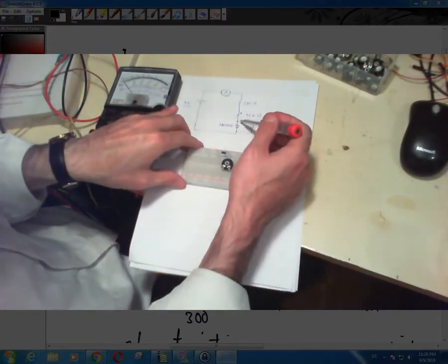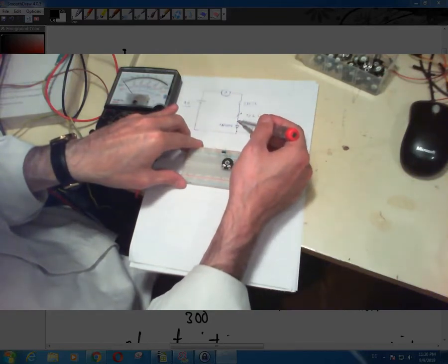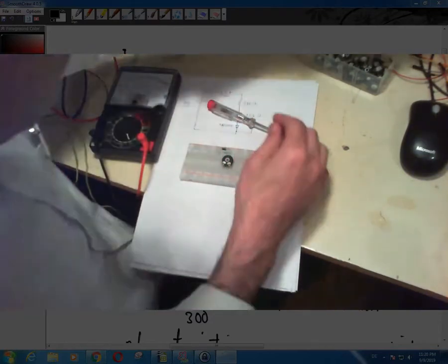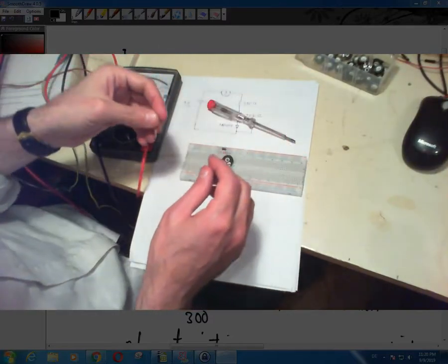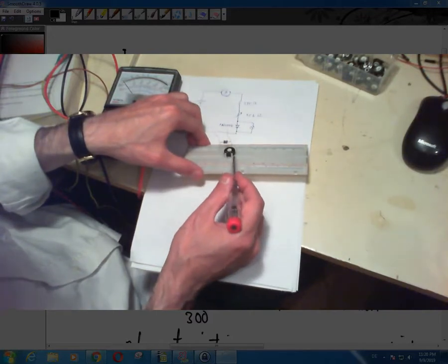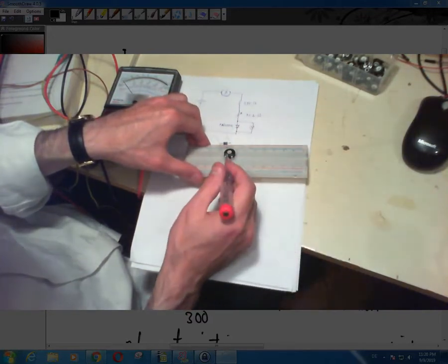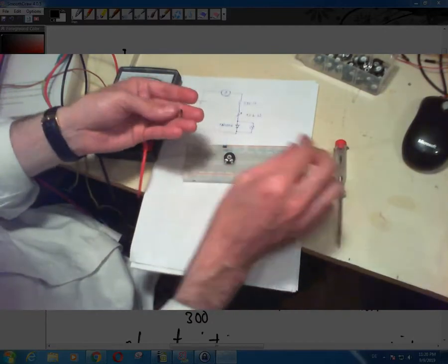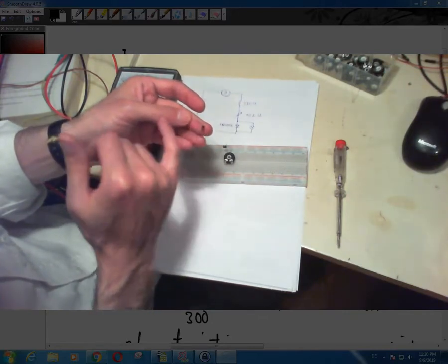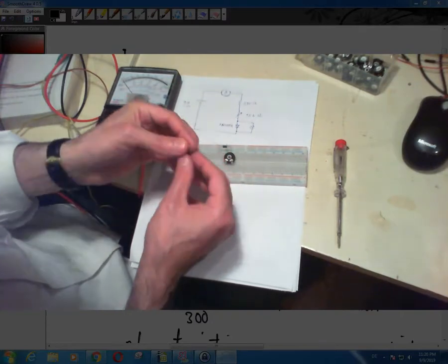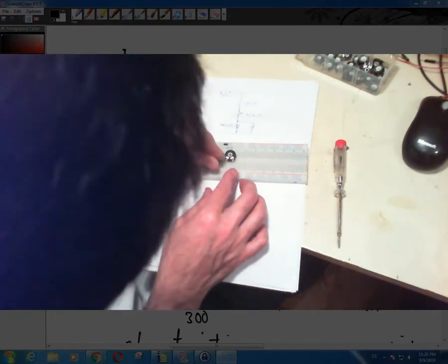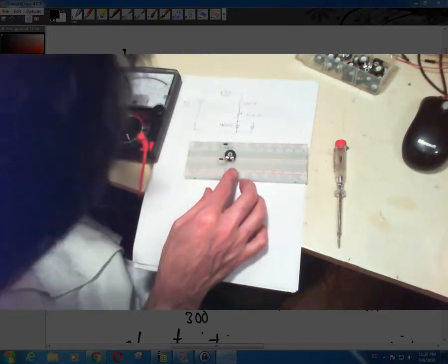And then you can see that the other end of this potentiometer is connected to the anode of the diode. So now my diode is over here, and I choose, for example, this end of the potentiometer. There are two ends. I leave this out, and I choose this end of the potentiometer. The anode of the diode is the one that doesn't have that color band. So I connect it to this lead over here.